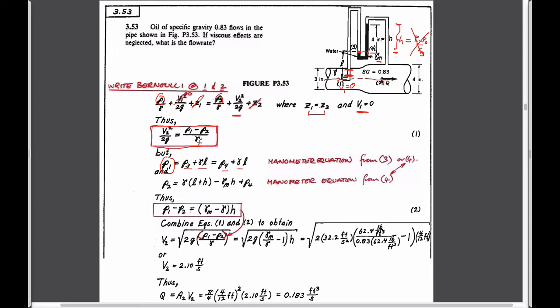We can also define the pressure here in terms of the system as well. In this particular case it would be P4, which is this term here. We go up a height, so subtract off H times the unit weight of the gauge fluid. We know that we can go across to this point here, and we go down a length which is going to be H plus L times the unit weight of whatever's flowing. So this clearly also is true. We end up at point 2, and we have this point. So we now have two pressures in the system.